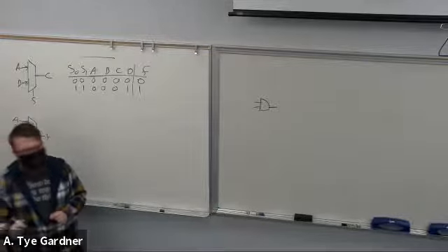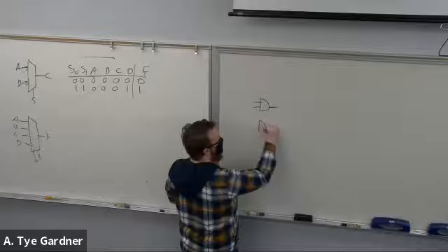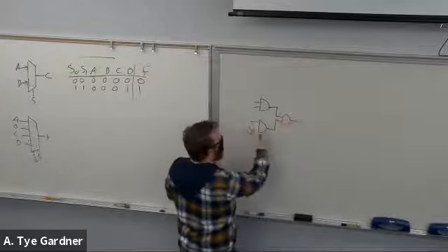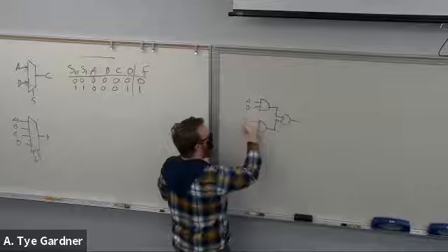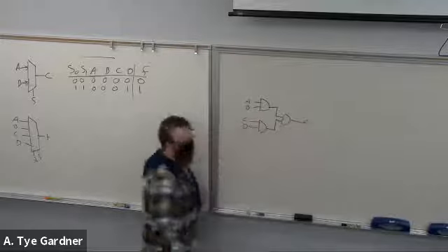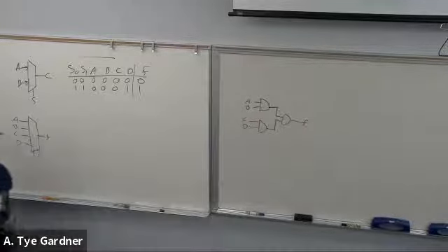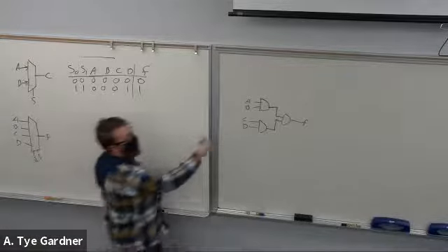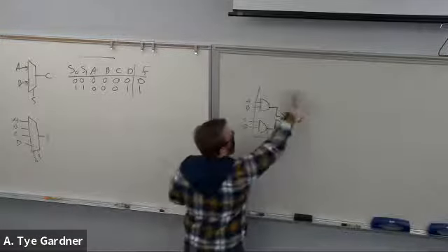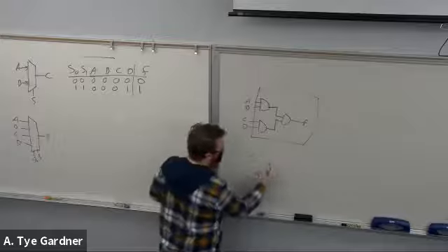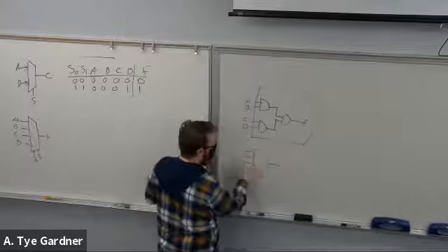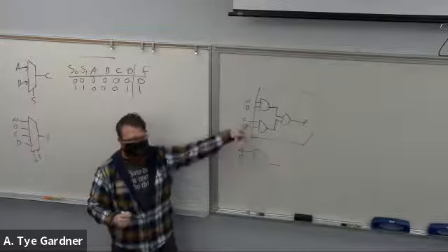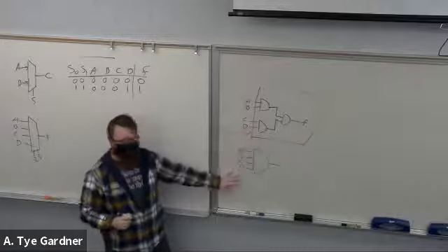Take another AND gate below it and try to tie two ANDs together. What do I tie together with? Get another AND gate. Perfect. There, a 4-input AND gate from nothing but 2-input AND gates. Now I could draw this as a schematic symbol. We know what's inside of this is really just 2-input AND gates, but I could draw it like this.